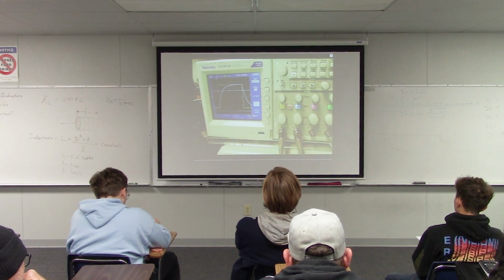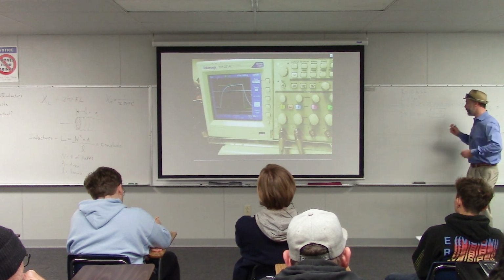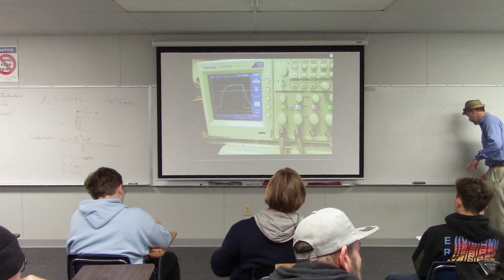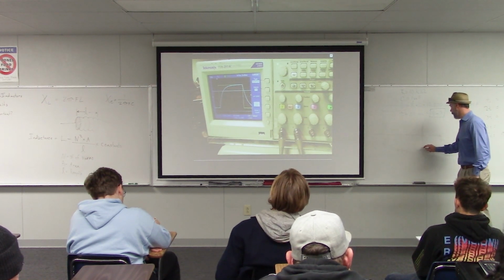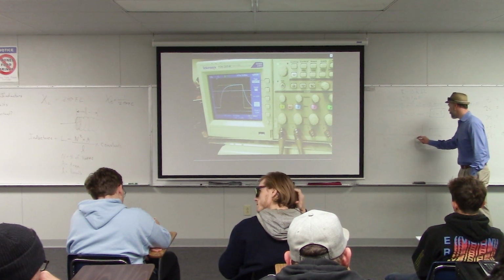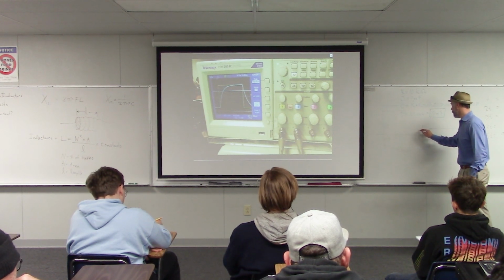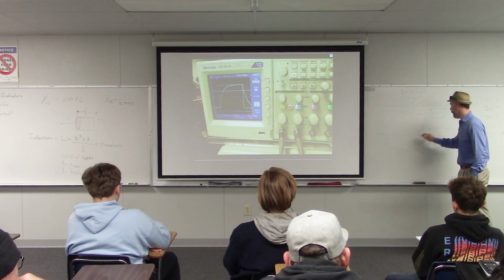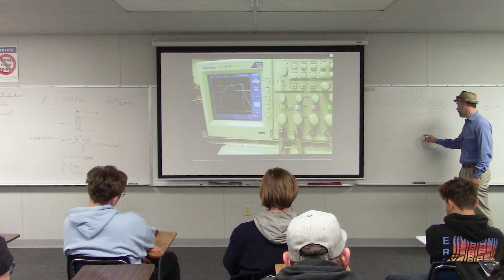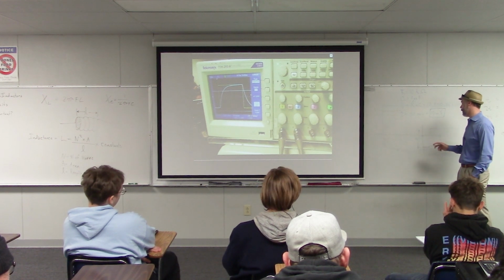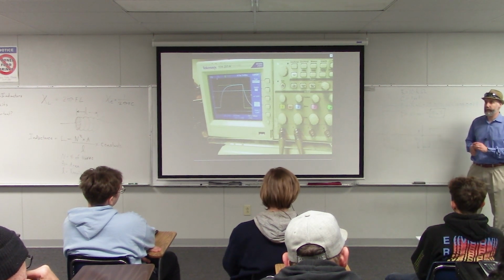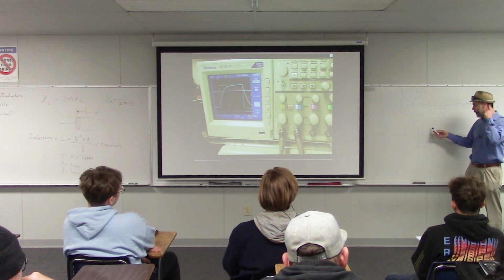So what we're going to do is choose our input amplitude to make our math a little bit easier. We're going to choose our input amplitude to be 10 volts. In other words, if we look at the input voltage, we're going to make sure that it's 10 volts from the bottom of the wave to the top. In other words, 10 volts peak to peak, because that way we know that 63% is just 6.32 volts. Okay, 63.2% makes the math really easy.